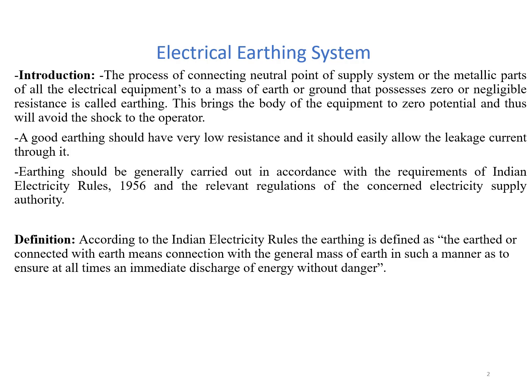So a good earthing system should have very low resistance and it should easily allow the leakage current through it. Earthing should generally be carried out in accordance with the requirements of the Indian Electricity Rules 1956 and the relevant regulations of the concerned electricity supply authority.